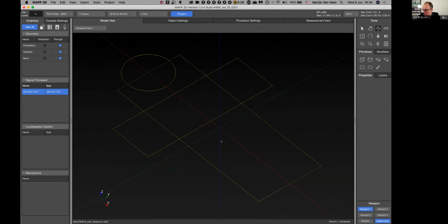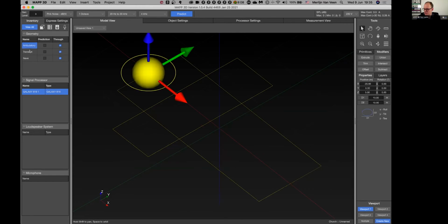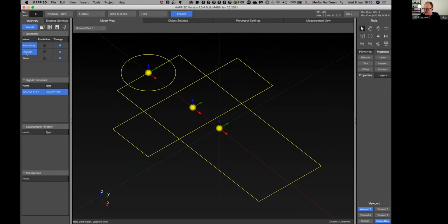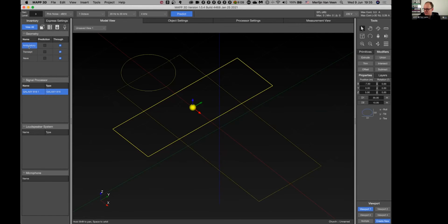In order to turn it into a single outline, we're going to use our first modifier, which is known as the trim modifier. And in order to use the trim modifier, we have to choose two two-dimensional shapes at once. We can do a drag and drop, or we can just use shift and choose both pieces of geometry from my inventory.